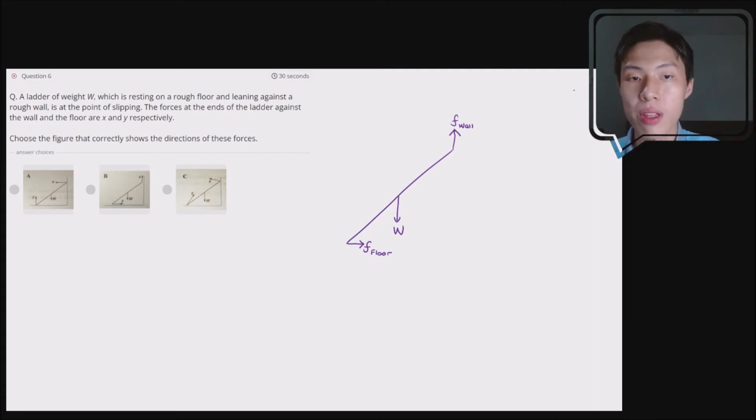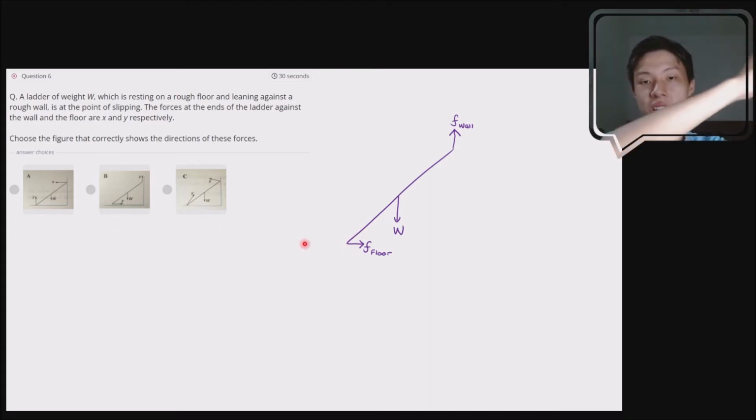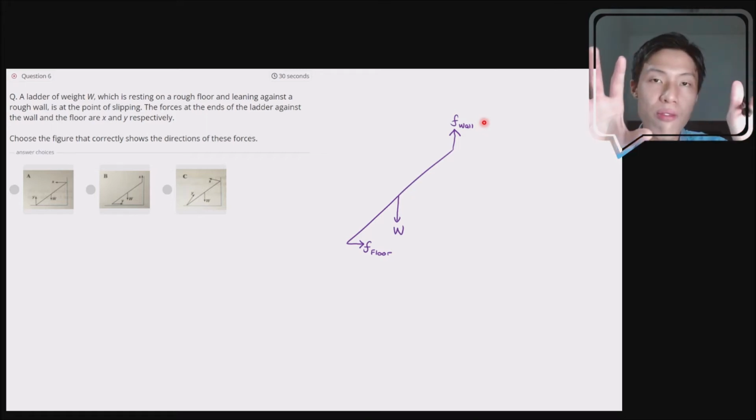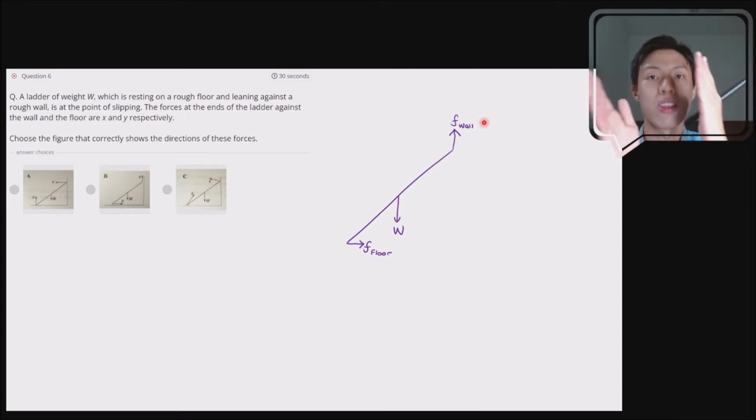Okay, so I believe that's the only two places where you have your friction. Next, you move on to the last question. Is there any hinge or is there any pivot? Well, you can consider this place to be a hinge because it is in contact. You can think of it like a hinge. So this one you can also think of it like a hinge. But in this situation here, because you have already considered the friction, that means you don't need to consider everything regarding reaction force. Okay, reaction force, right, is a combination of friction and normal force.